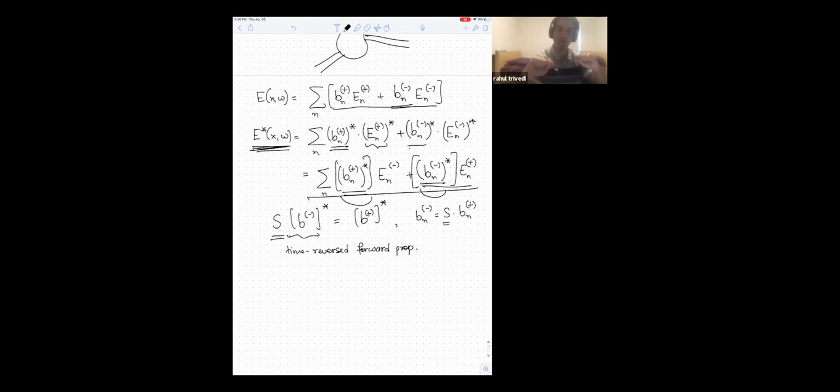So they became the forward propagating modes and I got another relationship between the forward and backward propagating modes. And you can see that if these two relationships need to be satisfied, then this immediately implies that the inverse of S is just equal to its conjugate. Okay, so this becomes the constraint on the scattering matrix as set by time reversal symmetry.